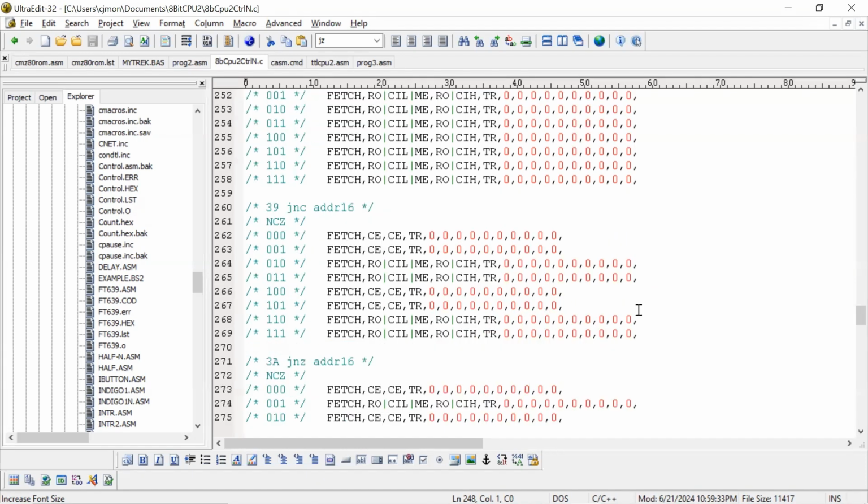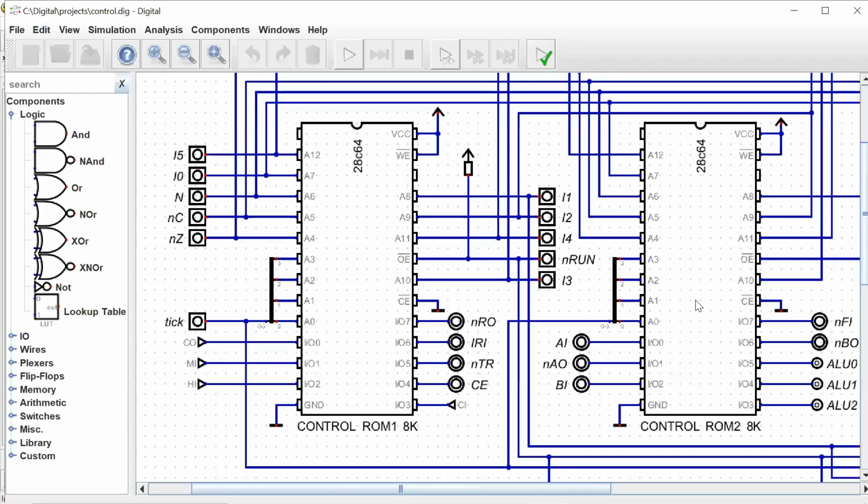But down here, you can see that this is jump if not carry. So we can see here's our carry bit, and the 16-byte microcode steps differ in the case when the carry flag is clear, or the case when the carry flag is set. So that's just a view on how that works and is organized, and it shows us how the ROM address space is used.